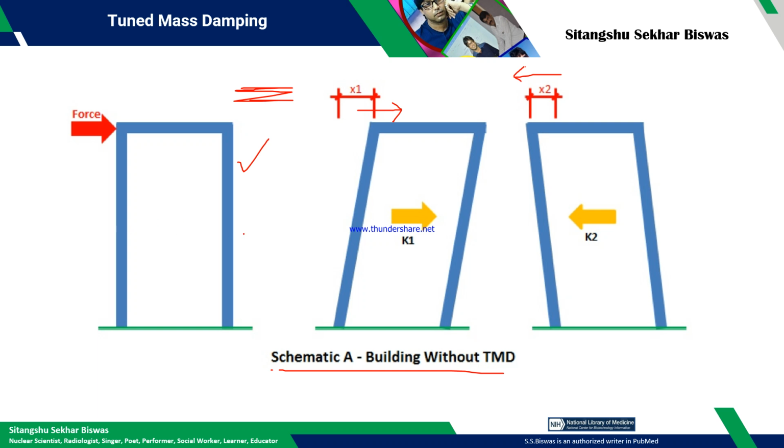There you first make the building, make the geometry, define the material based on the design, and calculate the eigenfrequency, that is, the natural frequency of the structure.